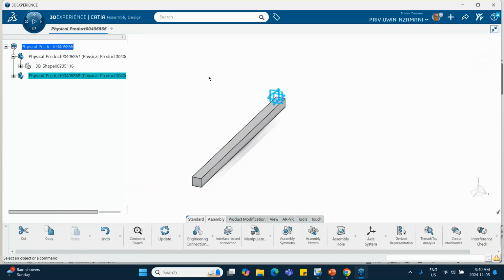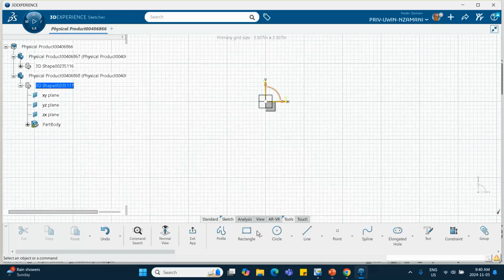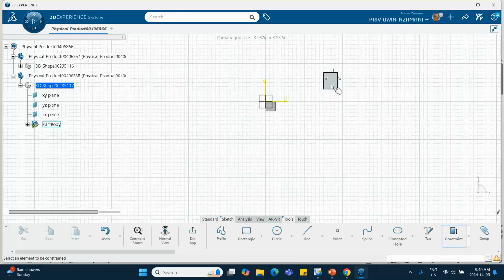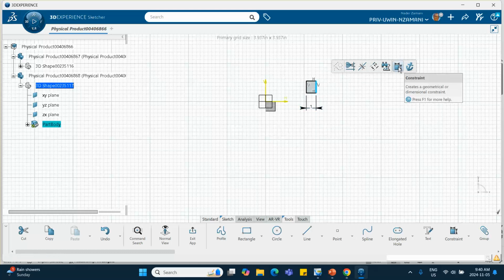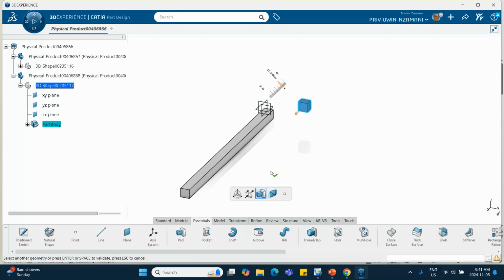That's going to be the block. So let me make the block. I go to part design here on a convenient plane. On that vertical plane, I will sketch a 1 by 1 square. You mentioned these things. Okay, this is also going to be 1. All right, exit and pad it by 1 inch. Okay, that's going to be the block.